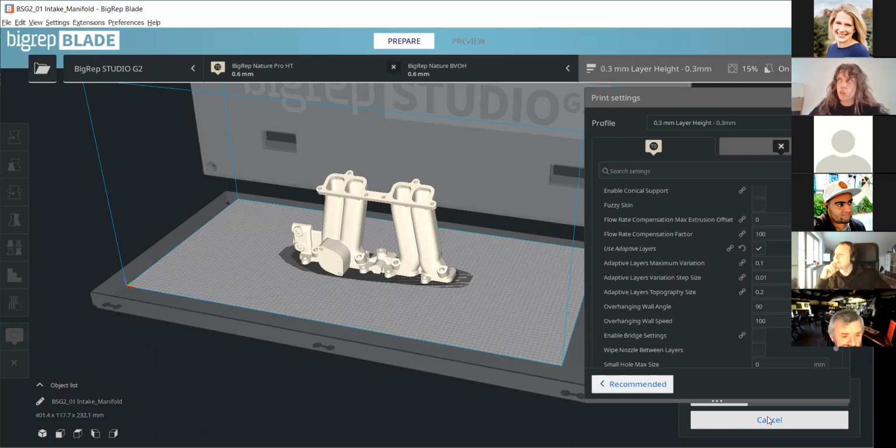So this really allows you to get the best surface finish and to possibly speed up your part. Again, it gives you the option to change the stepping size. You can make it even less. Change, again, the variation between layers. Obviously, if you're using the studio, you can't do a layer variation of 2 millimeters. That just won't work. You have to stay within what the options are.